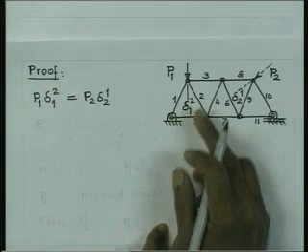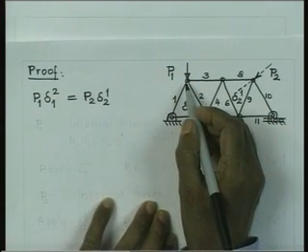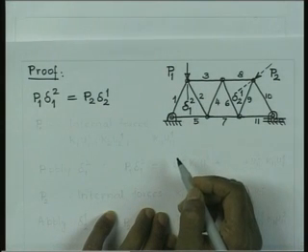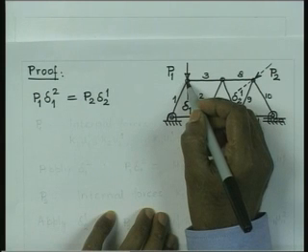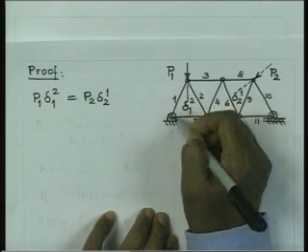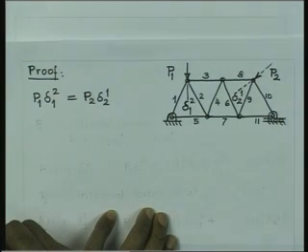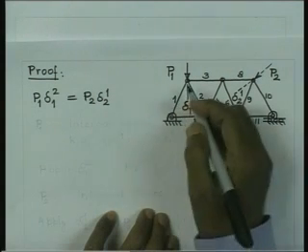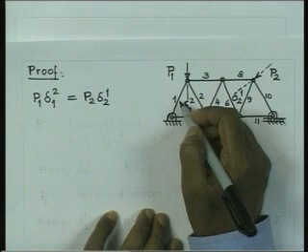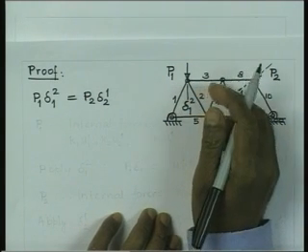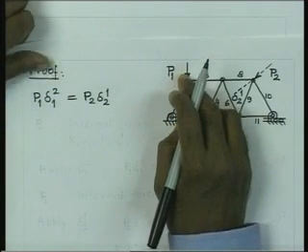Now, if I am applying the force on this structure here, this will give rise to some forces in each of these elements, and if we consider that this element is undergoing some deformation equal to U1 and the member has an axial stiffness equal to K1, then in that case the internal force that is going to develop in this element is going to be K1 into U1. Now, we will just try to consider superscript 1 to indicate that that is due to the force P1.